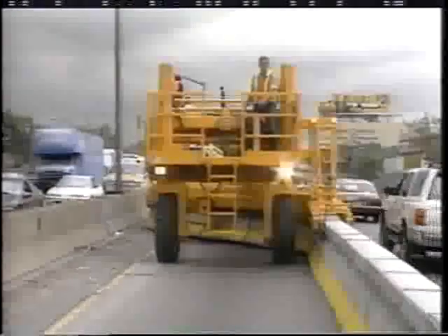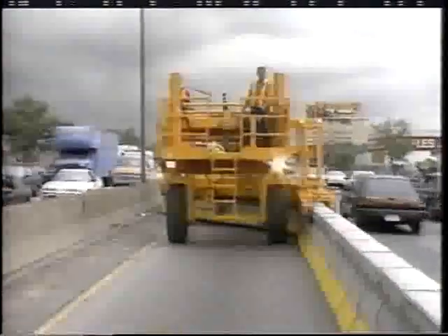The traffic was then moved across the median to run contraflow style on this newly created divided highway. The other side of the roadway was closed to traffic, and the contractor worked the full width of the road without interference. As the morning rush hour approached, the barrier is moved back to the median and the whole roadway opened to traffic. The temporary contraflow lane concept again allows work and traffic to be conducted in 2 separate areas of the roadway while minimizing congestion.